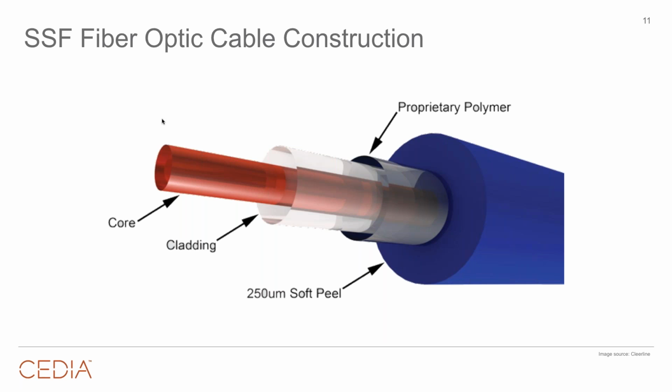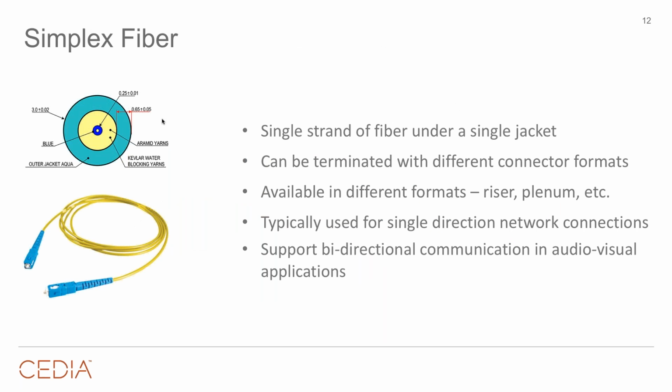Think of it in terms of that window on your house compared to an automobile window. You throw a rock at an automobile window, it chips. But the coating on the window keeps the windshield from falling apart, from that crack spreading, okay? That's what this polymer does in these modern fibers. It allows us to handle it roughly. It allows us to handle it with bare skin. It allows us to not worry about getting oils and debris, dust, things like that all over the fiber and having it not work. In my opinion, it's what makes the AV installation as robust as it is.